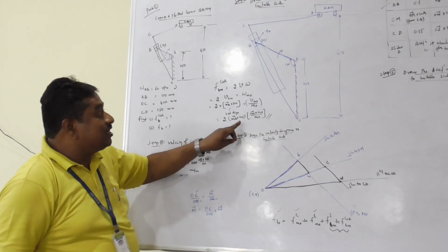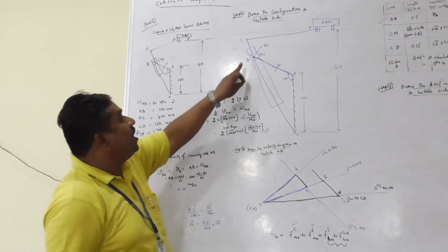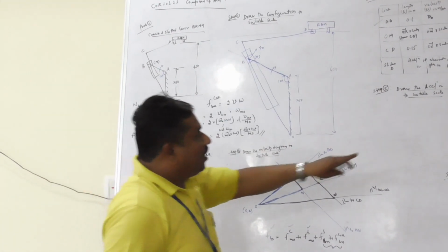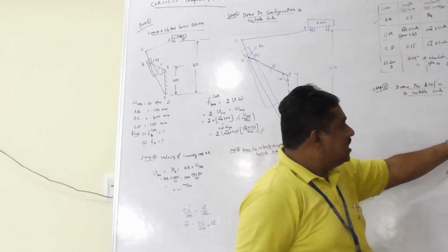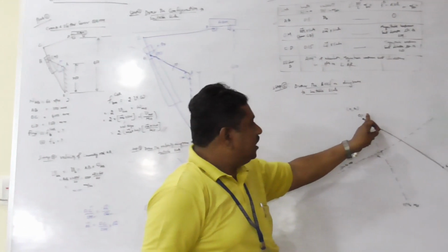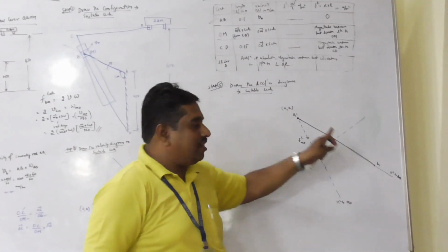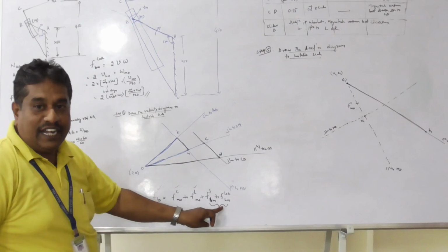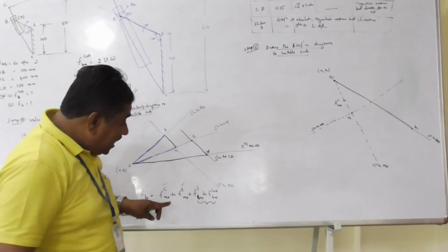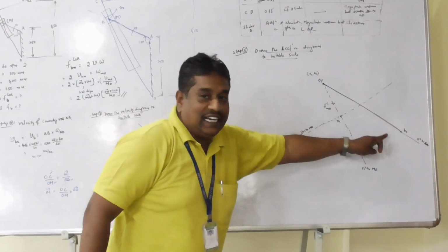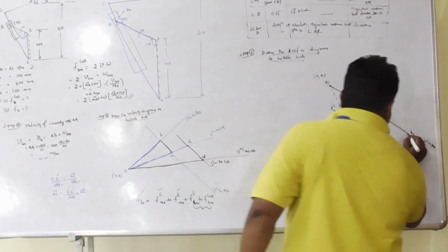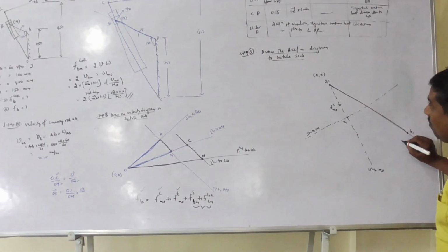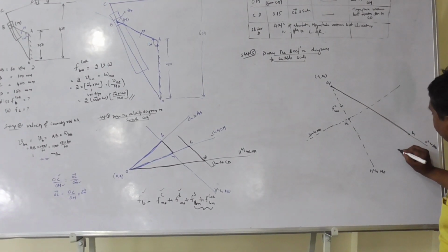Now the direction of this Coriolis component is perpendicular to the link OM. Therefore, in the acceleration diagram, since already I expressed the total acceleration of point B with the vector O1 B1, which is the vector summation of 4 quantities, the resultant of these 4 will be the total acceleration. Hence, at B1 for this magnitude, I draw a line perpendicular to MO.